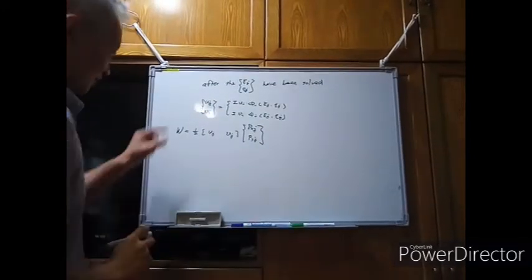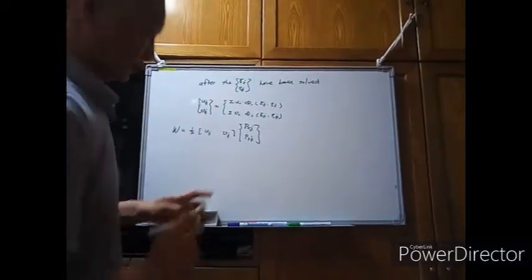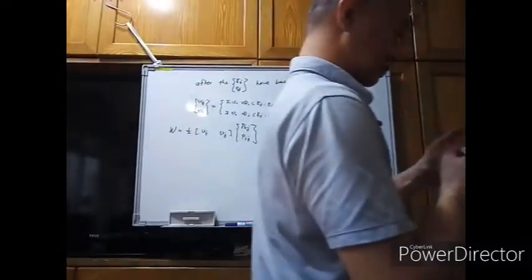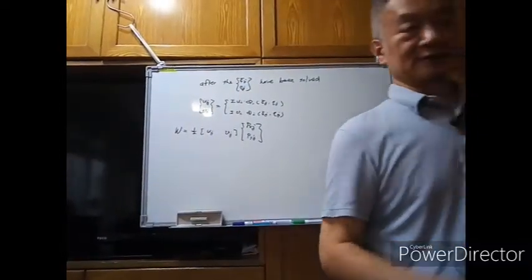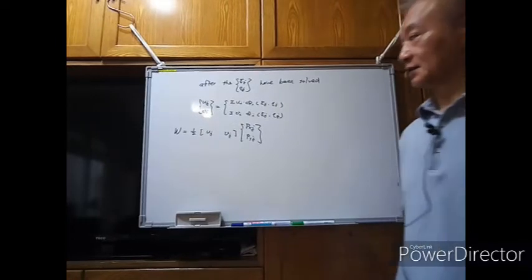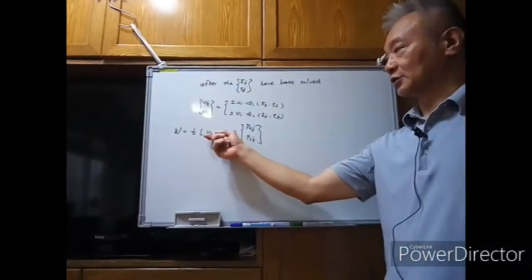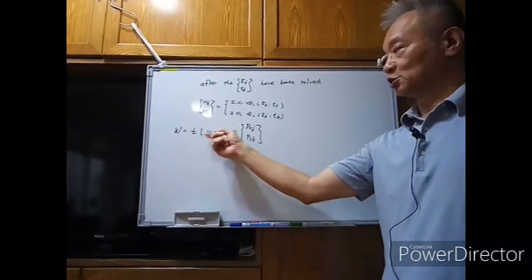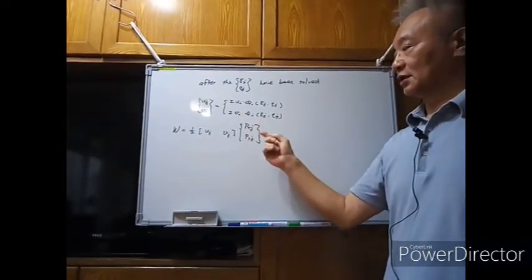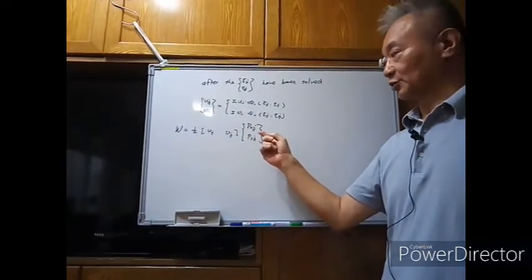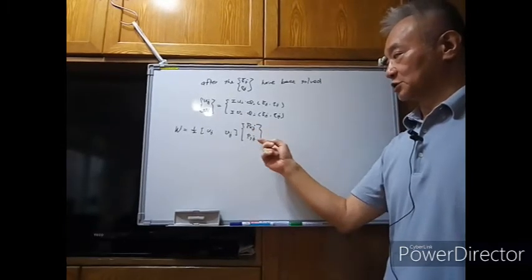Okay, if we would like to calculate the work done by the concentrated load applied at the point J, then we need to multiply the corresponding displacements uj and vj by the two applied loading components pxj and pyj.